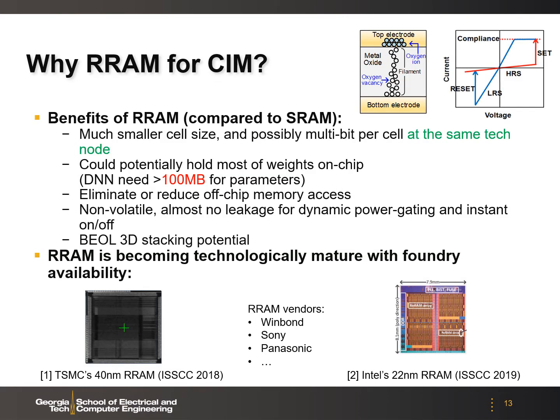Why RRAM for computing memory? RRAM is short for resistive random access memory, which is one of the emerging non-volatile memories. The RRAM structure is very simple, with two electrodes and an oxide layer in between. So the RRAM essentially is a variable resistor, where the resistance can be tuned by the voltages you apply. So we can encode the weights into the conductance of the device.